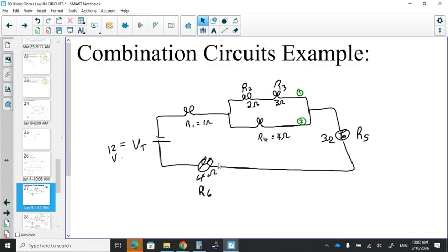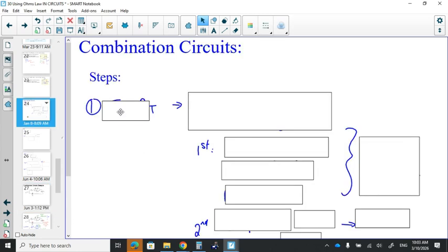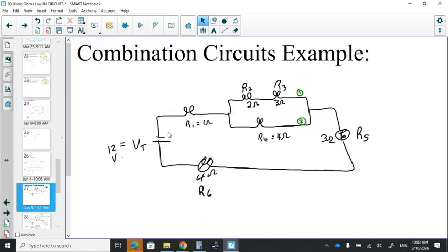And so all of a sudden you have your total resistance. So the steps that I say here would be, get your total resistance, of course, right? And again, in this weirder circuit, it's the typical one where I gave you the applied voltage and I gave you all the resistances. If I didn't do that, then instead you might have current, and you just use V equals IR to find stuff everywhere you can, right? And eventually the puzzle all fills in.